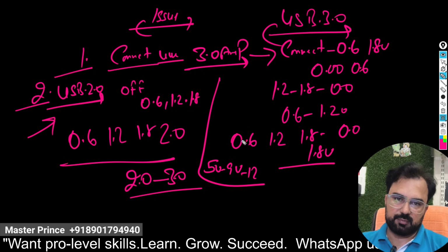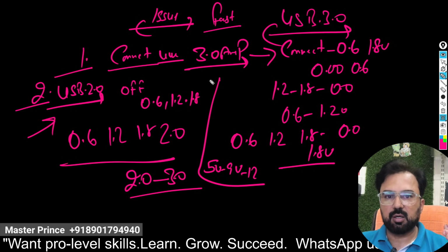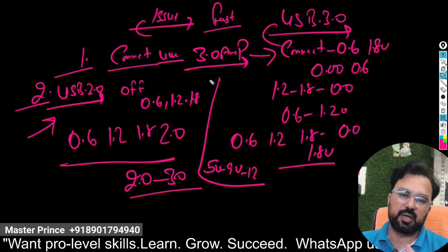Now this is the fault. On number 1, through this you get a clue, or you can say a hint. A USB, it means the fast charging does not activate. Whenever the phone switches to fast charging mode, from 5 volt to 9 volt, it drops to 0. Also whenever the current ampere goes from 2.0 to above 2.8 or 3.0, it goes back to 0 and again starts when the phone turns on.